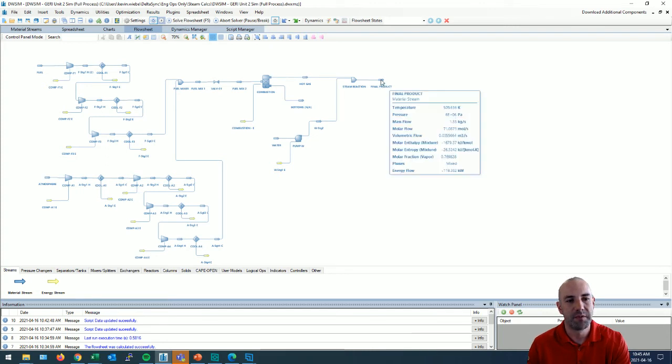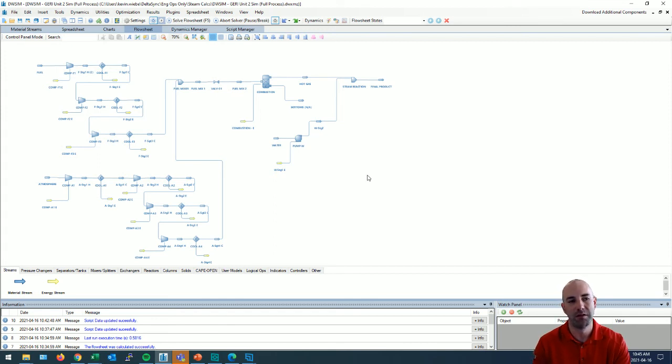The other thing here is you don't necessarily need boiler quality water in order to operate our direct contact steam generator. The water is added so close to the process, and it's all mixed together and sent downhole, that you don't have the effects you would have on a once through steam generator, where you've got the water on one side of the pipe and all the hot gases on the other, and you have this transfer of energy across a pipe where you're depositing minerals from the water onto the pipe continuously.